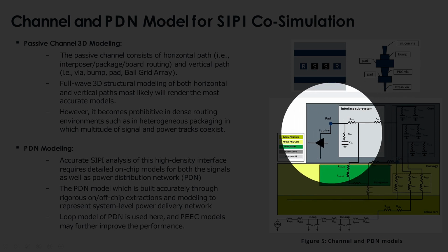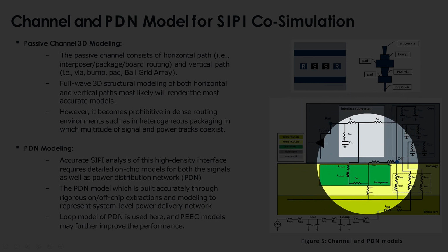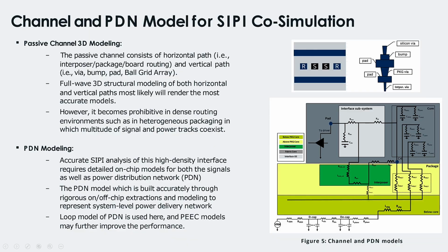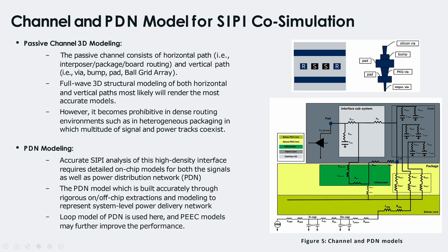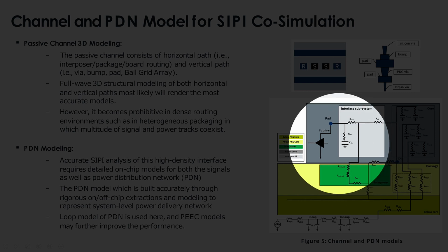So it's best to have a segmentized approach where you model your chip and silicon decoupling scheme if you have any model from your vendors, or internally developed models like CPM models, or if you are getting any decoupling schemes from the manufacturer, like you can add any MIM or MOM capacitance from the foundry. You also want to include all of those, and then go all the way to the package and the board.